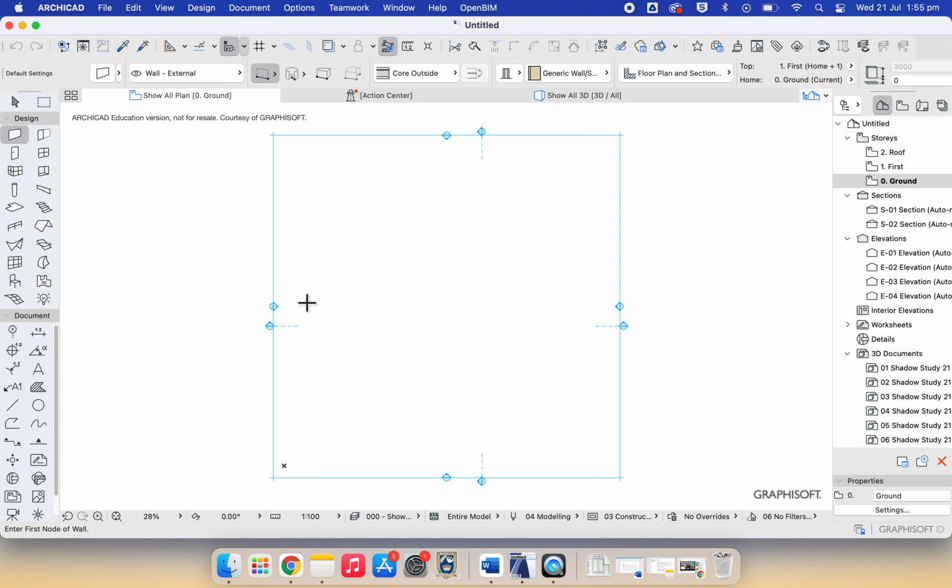Around this picture, this is where your building is going to appear as we progress. These arrows around the page are your north, east, south and west elevation markers. The markers with the lines coming out of them are your sectional elevation markers, which will be explained later.